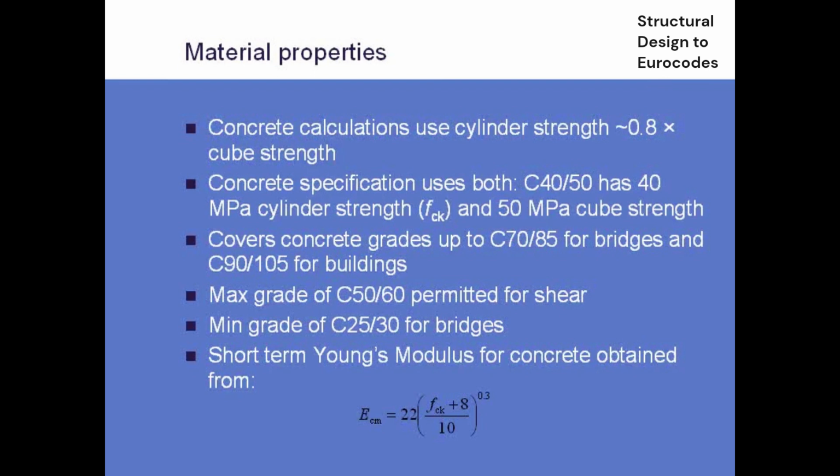The UK National Annex puts a cap in a couple of places on that, or well, specifically one place, when you're considering the shear resistance of sections without shear links in, the basic shear resistance. We mustn't use a concrete grade greater than C50-60 in the calculations. We can use higher concrete grades, but we can't take advantage of them in the calculations, which is due to some concerns with high-strength aggregates, which were there previously. They're not new, but we've just reflected that in the National Annex.